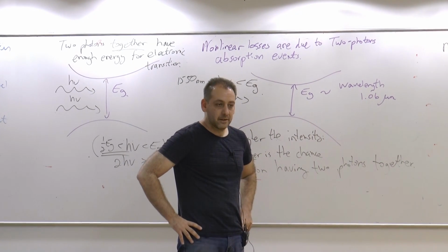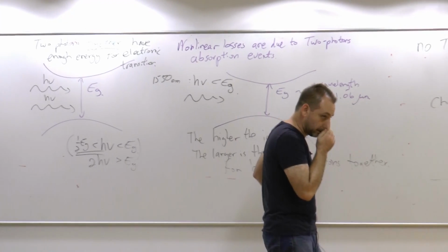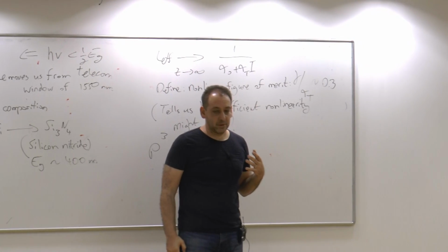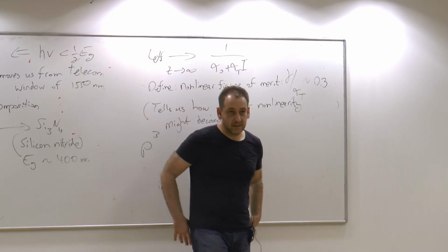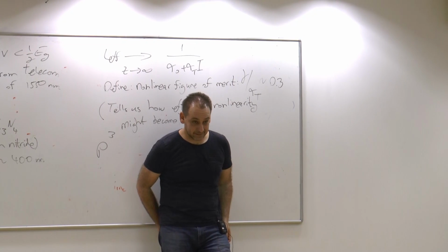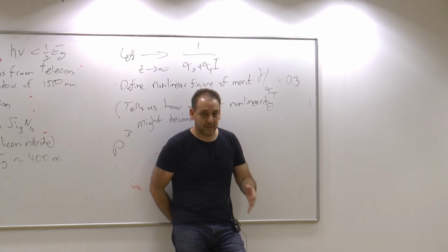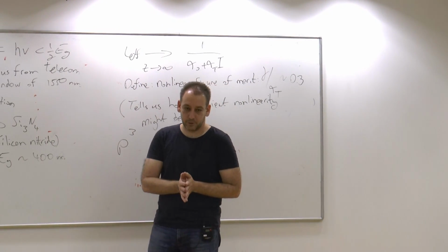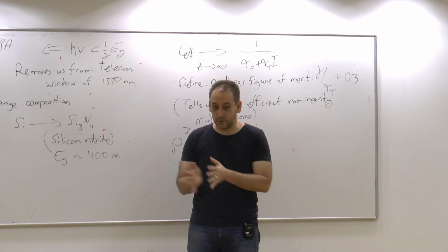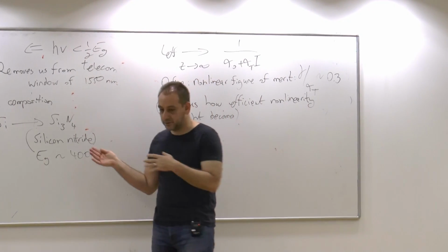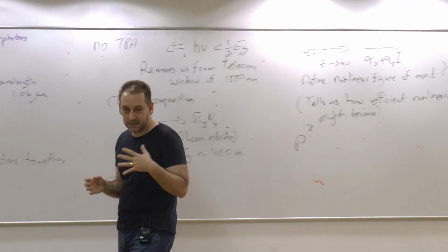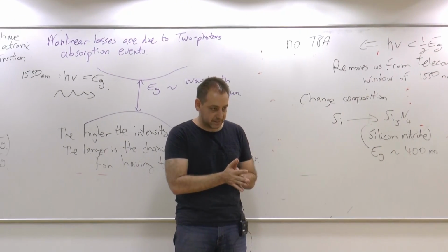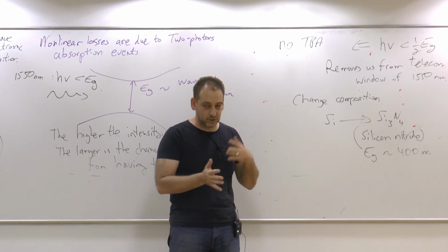Yes, please. What's the penalty? The penalty is that we are limited by power. Actually, when we turn to silicon nitride, the penalty is that you are no longer in silicon. That's the main penalty. Because again, a very big part of the appeal was to use the same stack of layers, the same material platform that you have in electronics. And now we do not. So if we turn to this solution, then part of the chip, at least, or all of the chip, has to be something else, something that is not CMOS electronics, and it's a big penalty, at least conceptually.